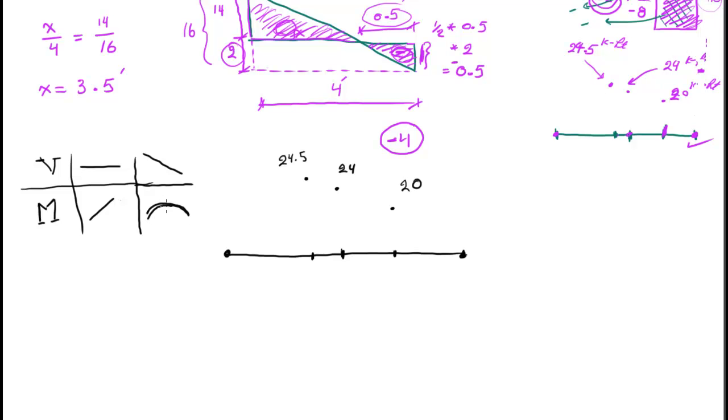Okay? It has to do with the one being the integral of the other, or if you differentiate this, you'll get the other. So I'm just skipping the theory behind it, but you can write it this way for you, just to remind yourself that if the shear diagram had a straight line, that means the moment diagram should have a straight line going up or down. I'm not claiming here it's going up only. It's going up or down. And if the shear diagram is an inclined line, or going down or going up, so the moment should have concavity, right, like this.